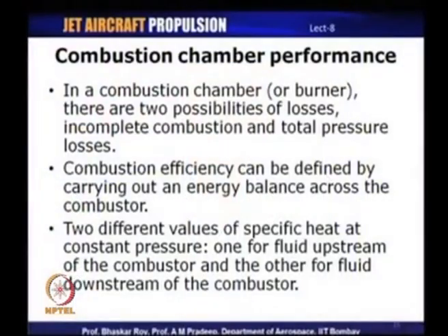able to define the combustion efficiency, because we know the combustion chamber outlet conditions, we know the temperature there, and so we know the enthalpy or energy content at the combustion chamber exit. We also know the energy content at the inlet, because we know the compressor exit conditions. We also know the amount of fuel that is added. So, based on all this, if we carry out an energy balance, we will know the efficiency associated with the combustion products. So, combustion efficiency we can define by carrying out an energy balance, and